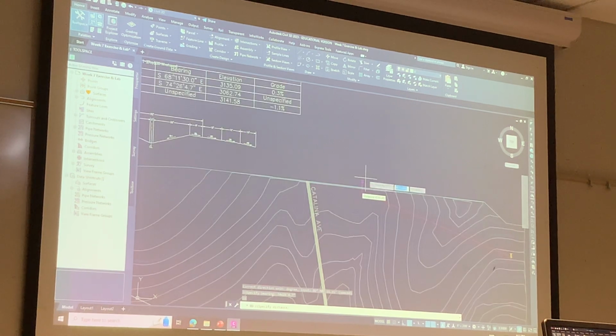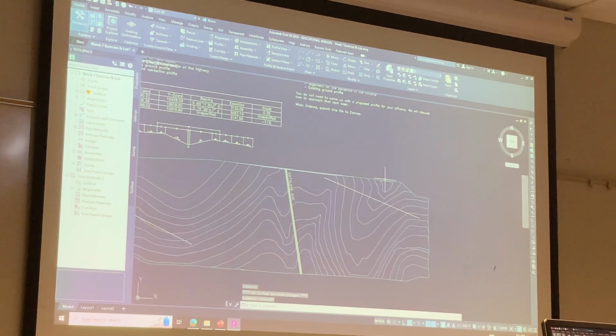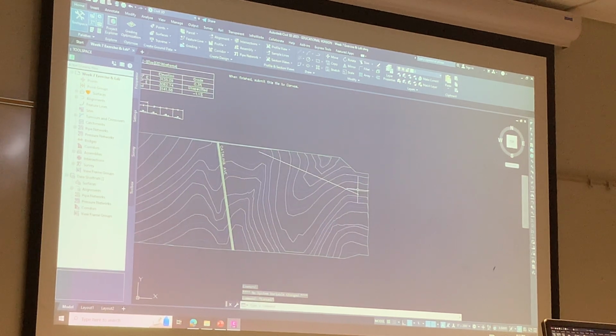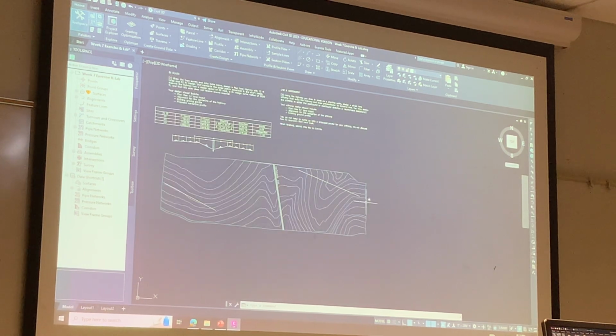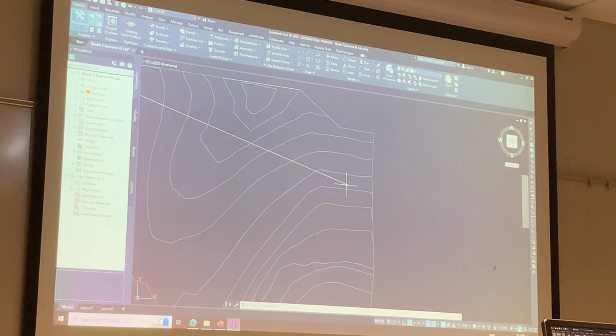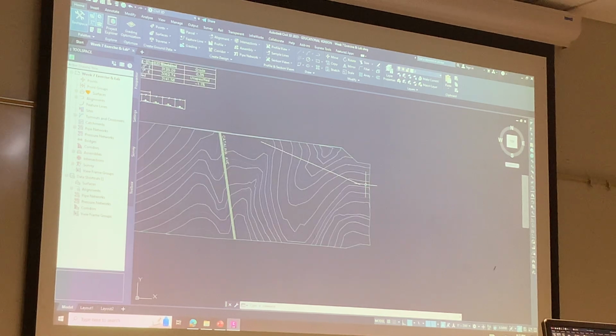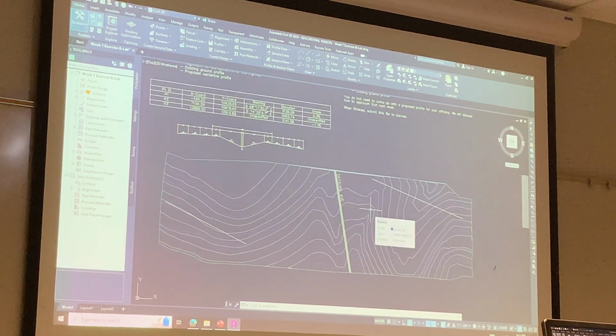So if you change the quadrant, we put it to that. That's fine. You want to make sure that you guarantee that you're going through this point. If you draw it this way down here, then there's a risk that whatever design you do, you could end up missing this point with some curvature or something. Because you want to designate that point, because that's the beginning and end of your stationing.